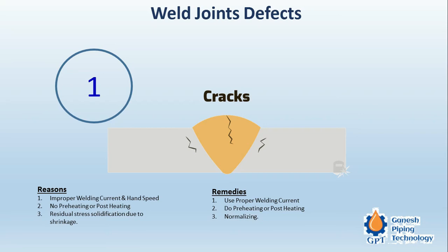So what is important as far as X-ray qualification is concerned, the joint defects are checked, and they should be within certain permissible percentage or limits. Now we are going to see one by one what these defects in welding are. So first an important defect is the crack. Crack is very common, and from the name itself you can get it that there can be some hair-like minute cracks. And why will this crack be there?